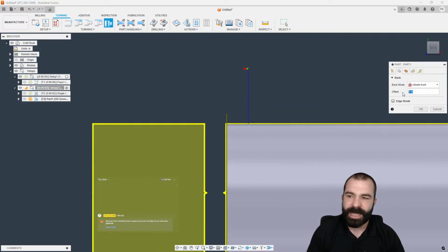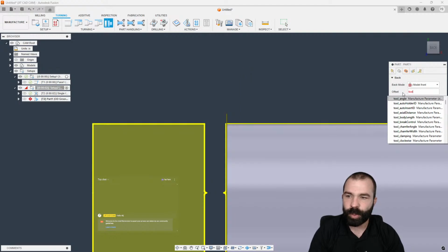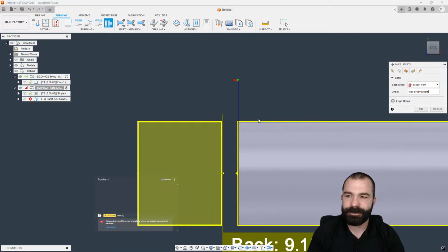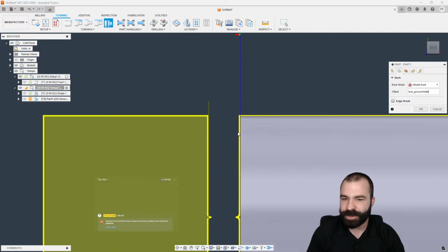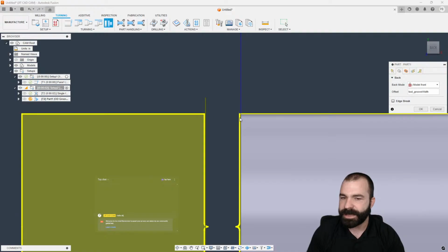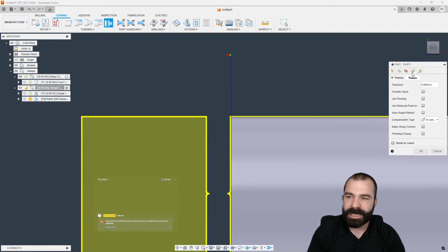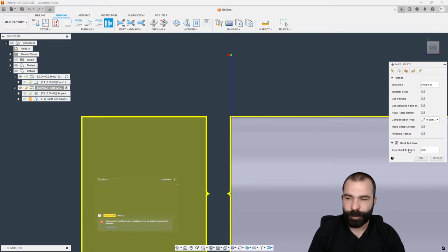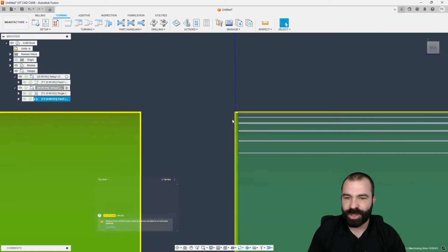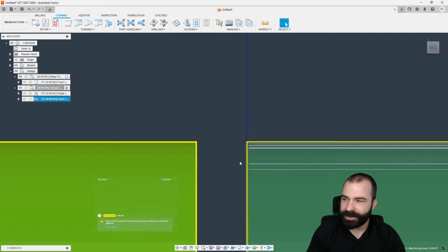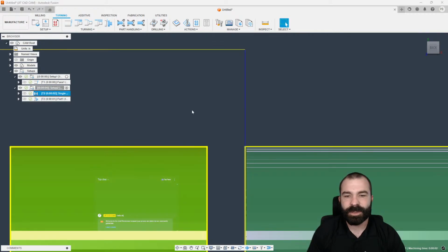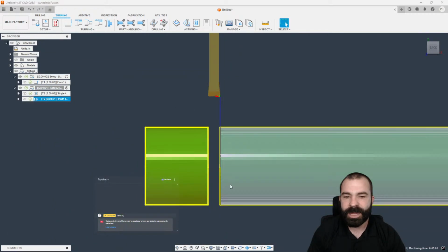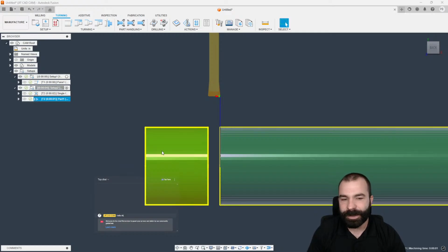And this is where you could actually utilize parameters like tool_groove_width. And now that is going to give me the total width of my parting tool. And as you can see, it's now slid me up to be in front of my part. And again, I could actually use stock to leave here once again, 5 thou, to push my tool further forward. Now in this case, we're actually going to type that in as a negative. And just like that, you can see that turning groove part off, same kind of scenario, same type of outcome, right? So again, single groove, we have turning part off, and just like that, 2 different scenarios to be able to get rid of that material.